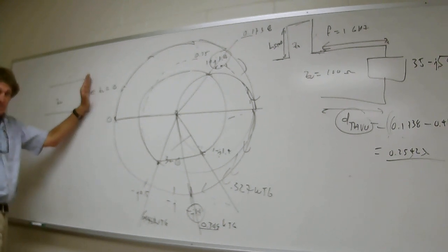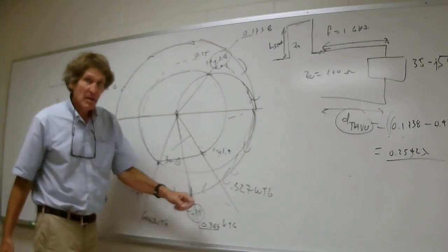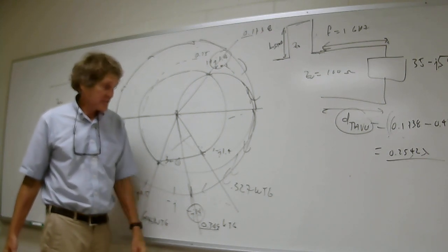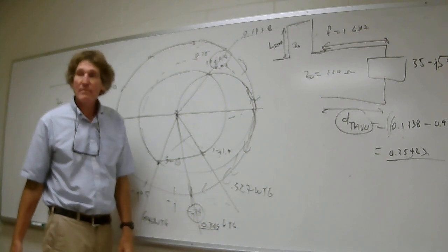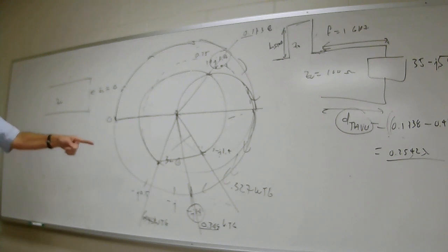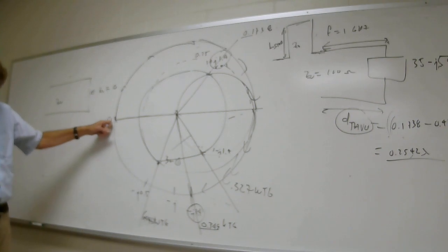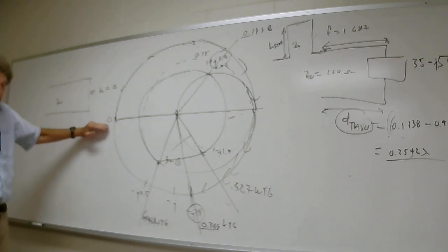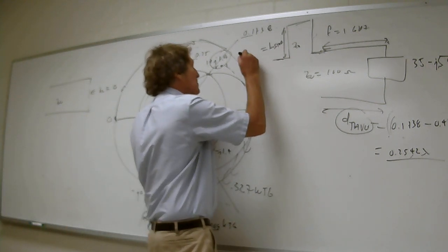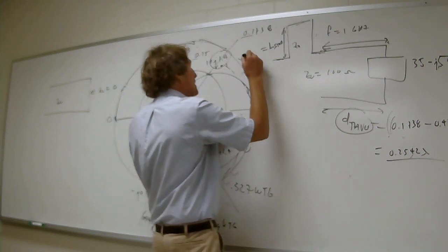So you got 0 divided by Z0 is 0, right there. Now you're moving, come down here, and you're going to get minus j1.4 at a distance of 0.327 wavelengths towards generator. Can you all see that? Now, the line length is that, 0.327. It would be the length of the stub, because here it's 0. Can you all see that as the 0 point? Literally, it's 0 here. So we move that far, that's how long this stub is.